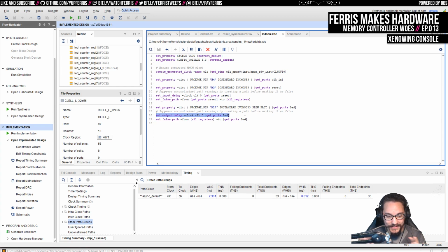But it's going to do its best in the synthesis and the place and route, and then at the end it's going to do a timing report on the actual design after it's done its best, and it'll tell you if there's problems. So I guess what I'm trying to say is, and what I wish I had done when I started getting into FPGAs, is I just was like, well, let me write some Verilog and let's figure this out.